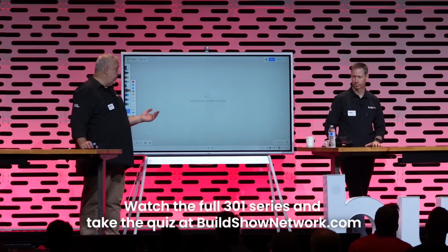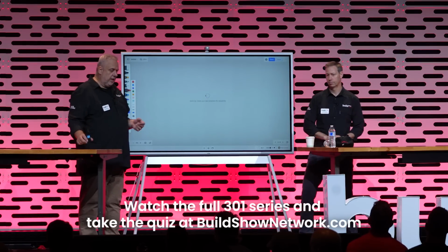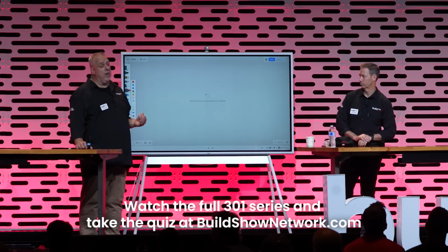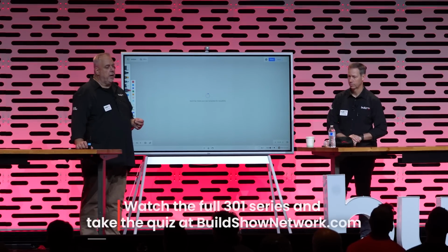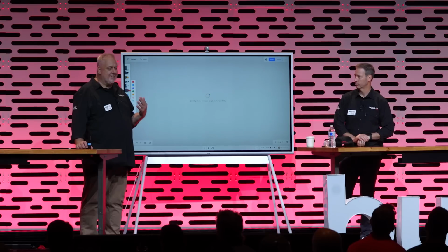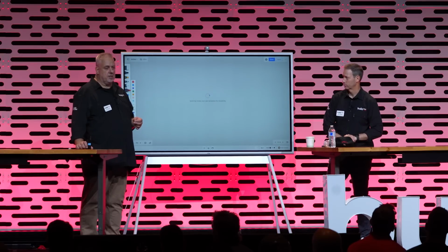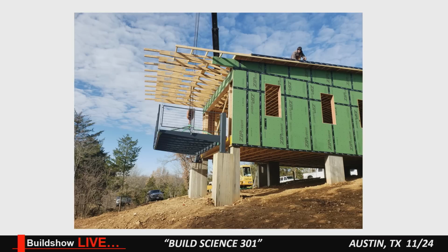Now, we do have the benefit of a floor frame being 16 inches here, so we get a whole lot of insulation by virtue of it being a floor frame. But that floor is exactly the same challenge as the wall. And this one here, when you're talking of solutions, problems, is an elevated house on piers, but I still think we're at like 0.30 or something on airtightness, which was pretty incredible given that we have that whole exposed slab to the outside.